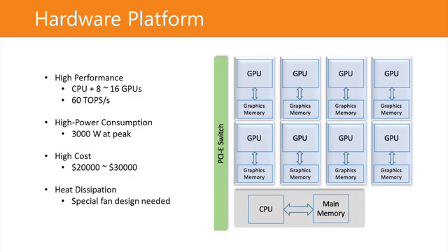That's all generation 1 autonomous driving. They have a similar design for the computing platform. Usually they have a very strong CPU, the highest-end Intel server-side CPU for computing. And on top of that, for deep learning and for localization tasks, they offload a lot of workload to the GPUs for acceleration. So they have multiple GPU cards. To build an industrial computer like this usually takes $20,000 to $30,000. And then it consumes thousands of watts of power at its peak.